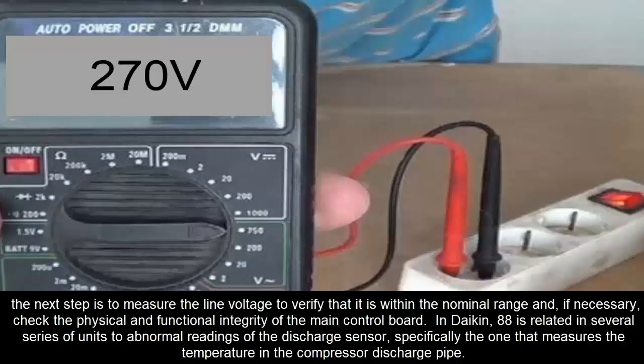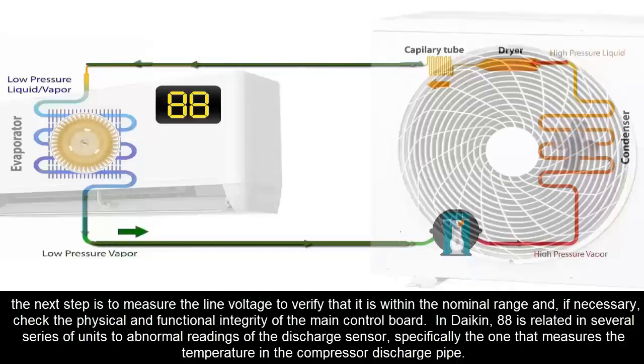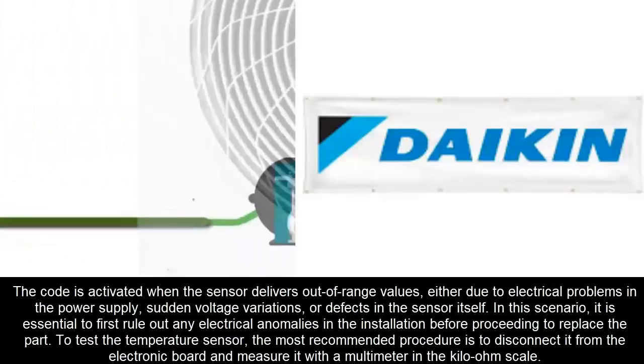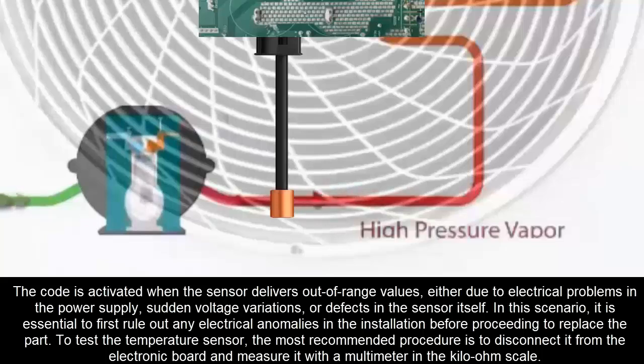In Daikin, 88 is related in several series of units to abnormal readings of the discharge sensor, specifically the one that measures the temperature in the compressor discharge pipe. The code is activated when the sensor delivers out-of-range values, either due to electrical problems in the power supply, sudden voltage variations in the grid, or defects in the sensor itself. In this scenario, it is essential to first rule out any electrical anomalies in the installation before proceeding to replace